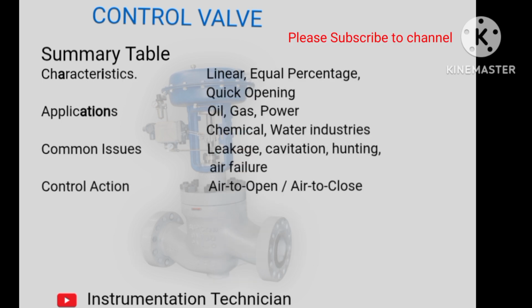Characteristics: linear, equal percentage, quick opening. Applications: oil, gas, power, chemical, water industries. Common issues: leakage, cavitation, hunting, air failure. Control action: air to open, air to close.